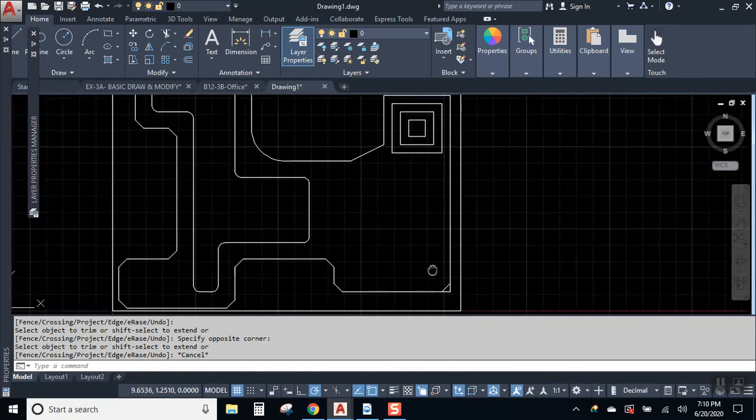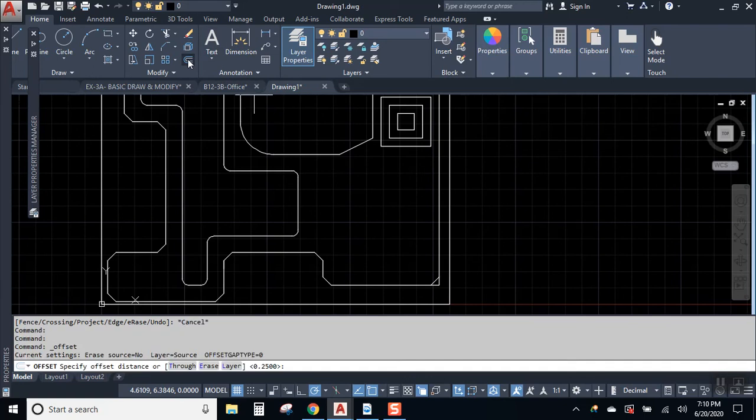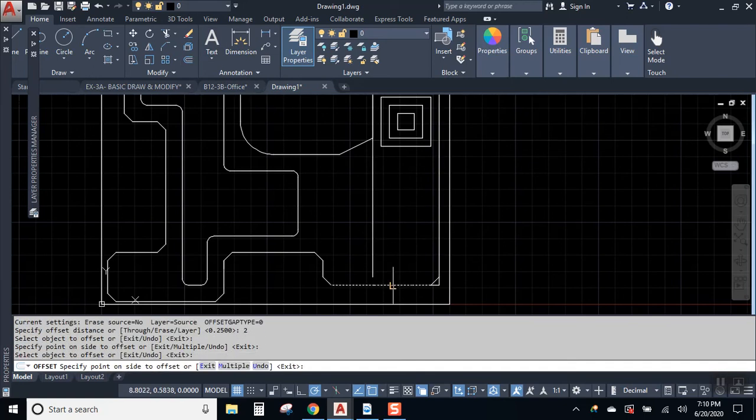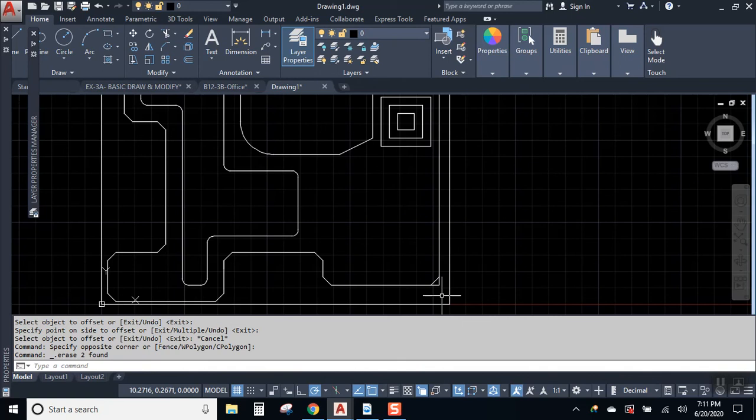And you can create that circle a whole bunch of ways. You can create that circle down here in the corner and then move it over and move it up. You can create that circle using the offset to find out where the center location is going to be. You can even create that circle using coordinates if you can give it a start point to work off of.